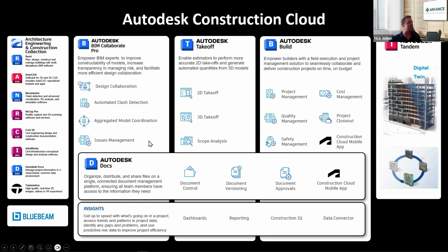I've also added on the bottom left here an extra, Bluebeam. Now, that's not Autodesk, but Bluebeam can also tie into AutoCAD. It's a little bit less automated. It won't use things like the Construction Cloud or your Autodesk web applications. What it does is force you to use a manual process, but it kind of feels like XREFs, if I'm honest. Bluebeam still connects, you can still do things, and it still kind of automates, but it very much feels like an XREF, if anybody was wondering.